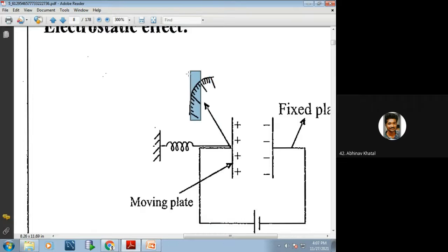And overall, full scale deflection. No, no. See, I'll repeat again. This one is the null position, this one is full scale, and this one? Sorry, sir. Calibrated scale. Okay, because we have certain readings over here: 1, 5, 10, 20. 20 is my full scale deflection, 0 is my null deflection. This is my calibrated scale.